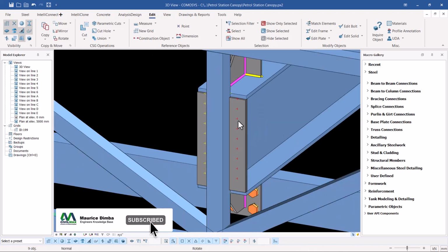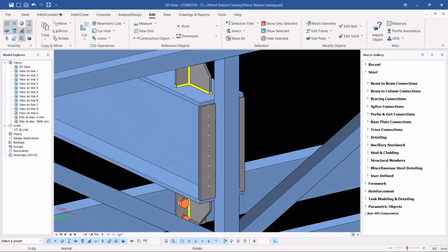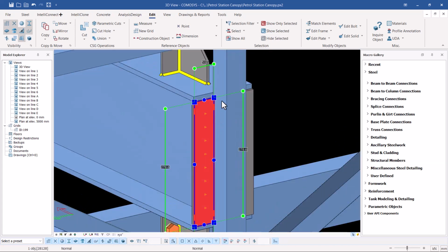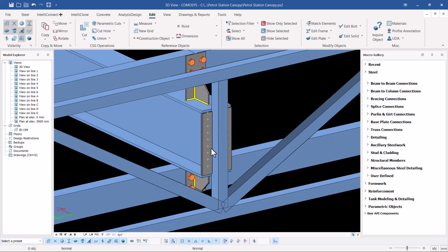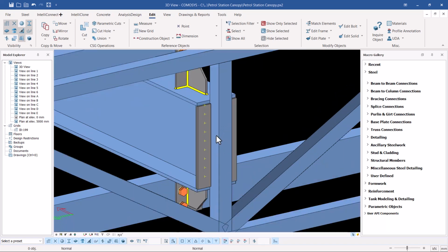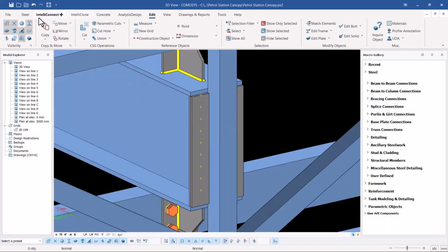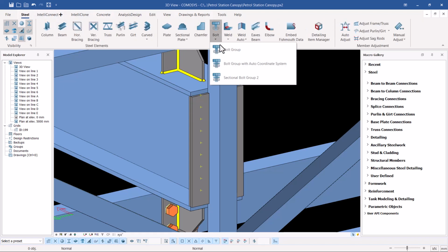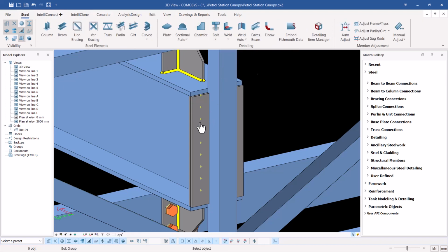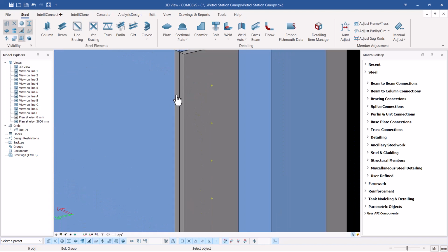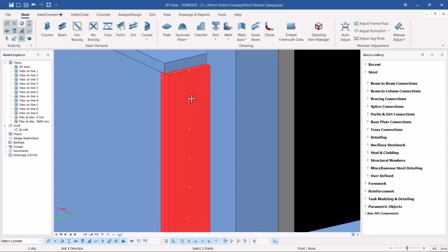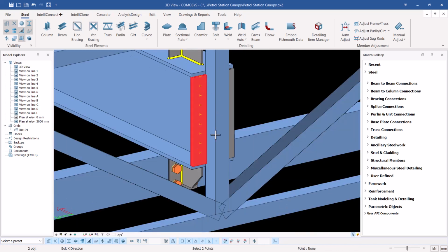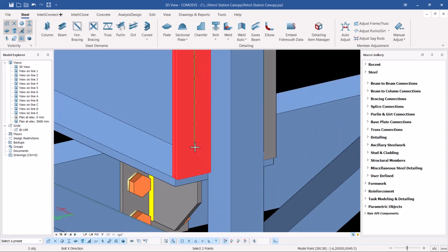So what I'm going to do once again is go straight to place the bolts. Remember, this plate is welded to this, and the other plate is welded to the rafter there. So this girder will be taken and fixed on site right away by bolting. So I'll come to steel, then a tool under steel, and pick the bolts. I'll pick the parts I want to bolt, these two plates. I'll right click, snap on that spot and move all the way to the bottom end here and snap right there.